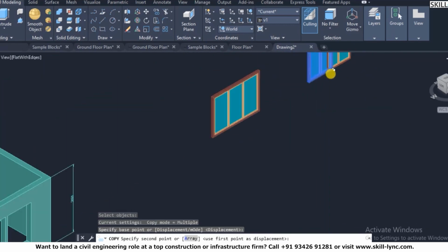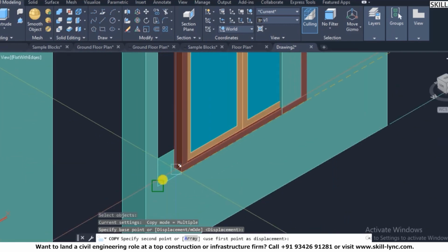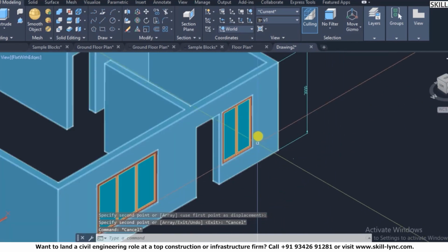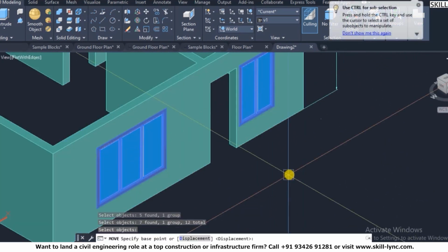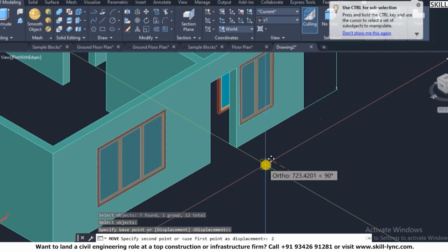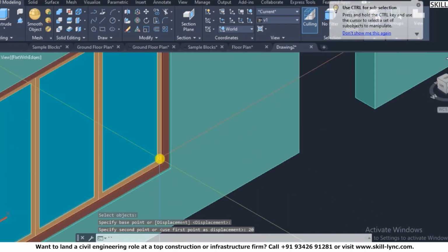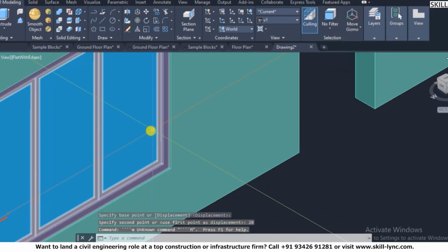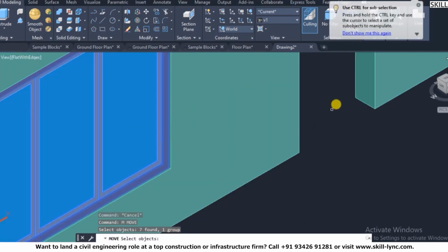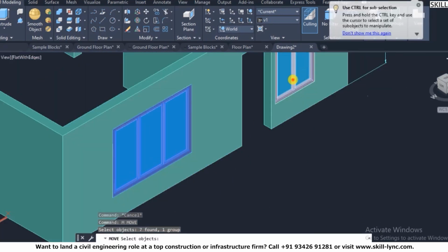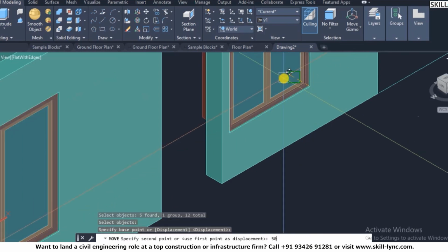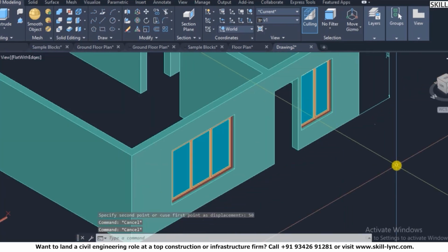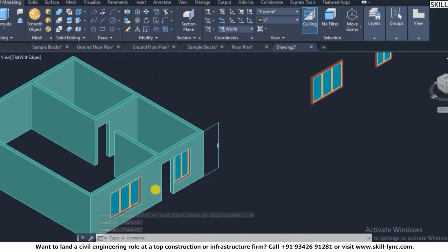This way you are basically placing the window into the opening. Now what you need to do is just place this 20 mm back, or you can create more niche to the side, so you can have this. So I would be moving more 50 mm in fact, so that it goes inside, right? So this is what I have created for the windows.